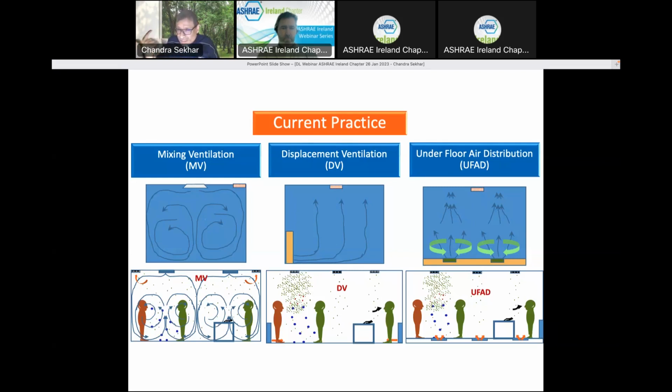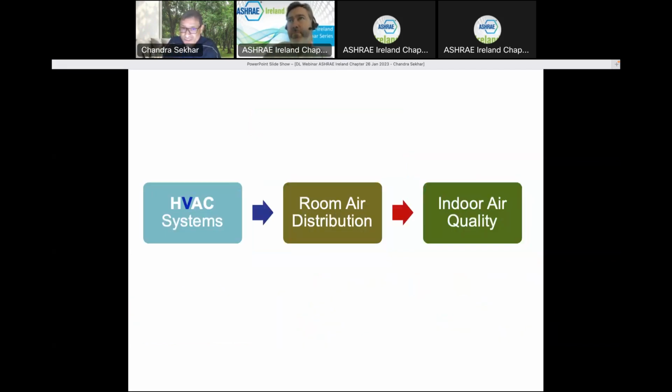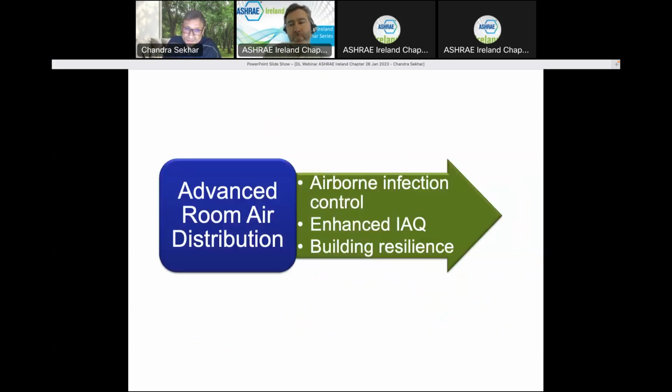However, once we dilute everywhere in the room within the room context in the sense that we just spoke about, it also needs to be removed out of the room. So we can't just use mixing ventilation and say that everything is diluted from the localized zone. There has to be a proper exhaust air ventilation, outside air coming in to exhaust that room air. It is an important part of the overall air distribution, resulting in how we can manage using simple conventional air distribution strategies. So I just spoke about the importance of ventilation. That's what this slide is really talking about.